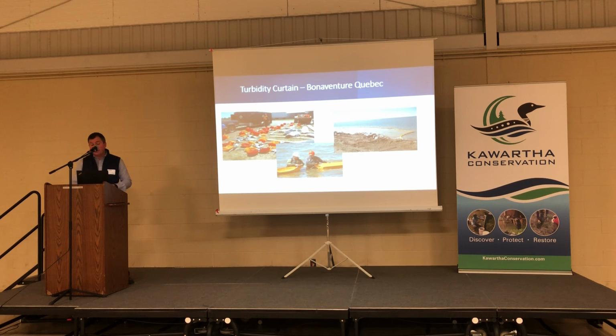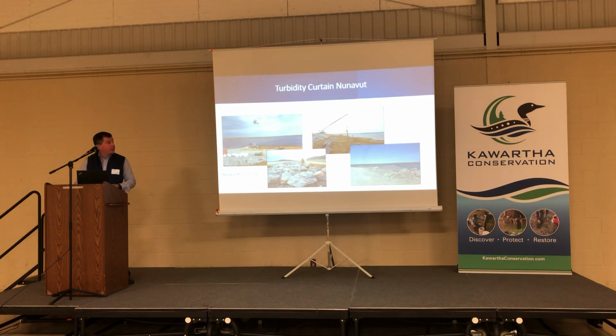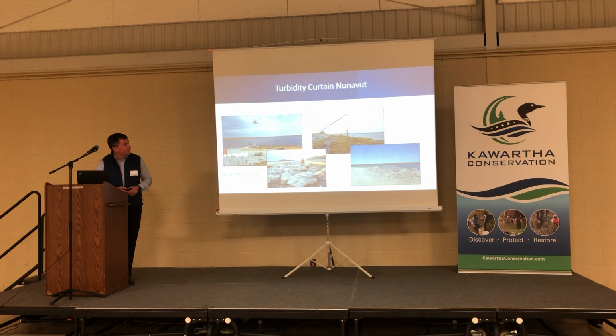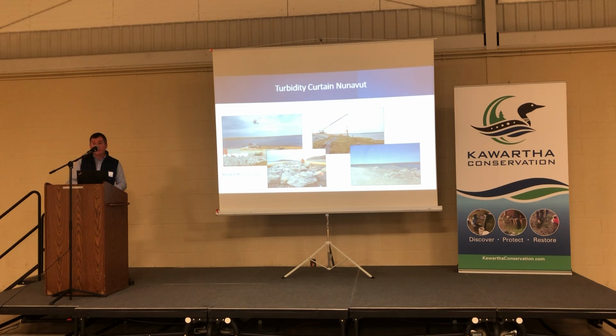Here is the project in Bonaventure, Gaspé Peninsula: staging area, inflating all the floats, installers in the water. They're fortunate to be shallow enough. They were able to get in there at low tide, make the connections properly, and the end result is a very effective installation. And as I mentioned, being in the tidal zone certainly allows the curtain to rise and lower. This one here at Nicoego up in Nunavut, they were able to borrow their helicopter to use ballast rocks instead of anchors, dropping them in place. These curtains were in excess of 50 feet, so they were massive curtains to be in place.